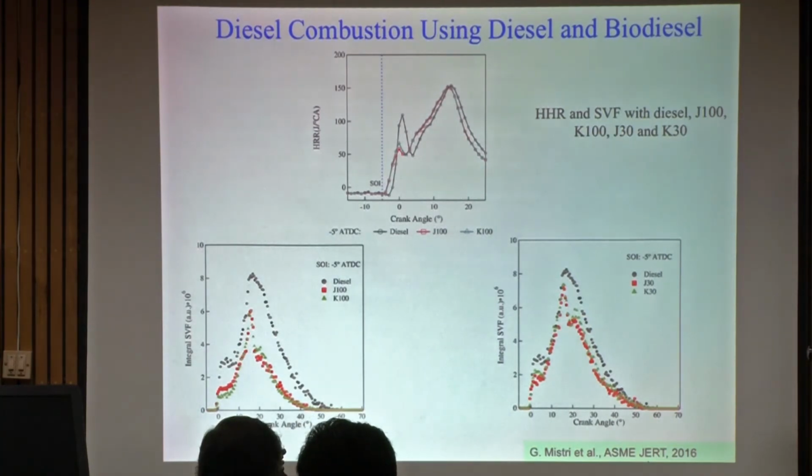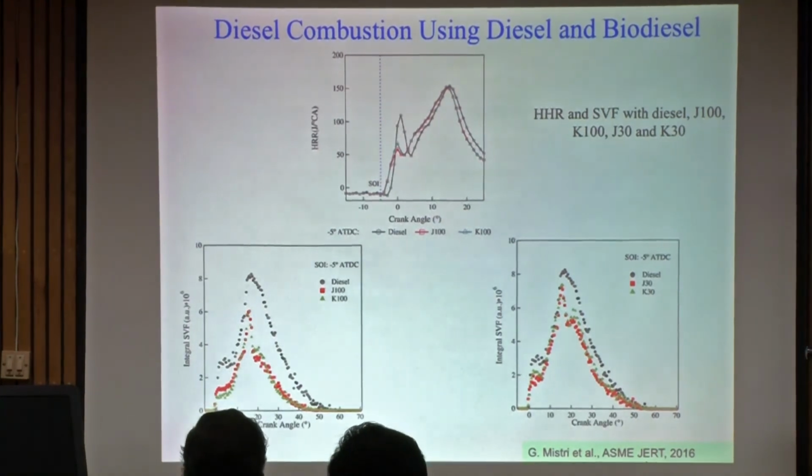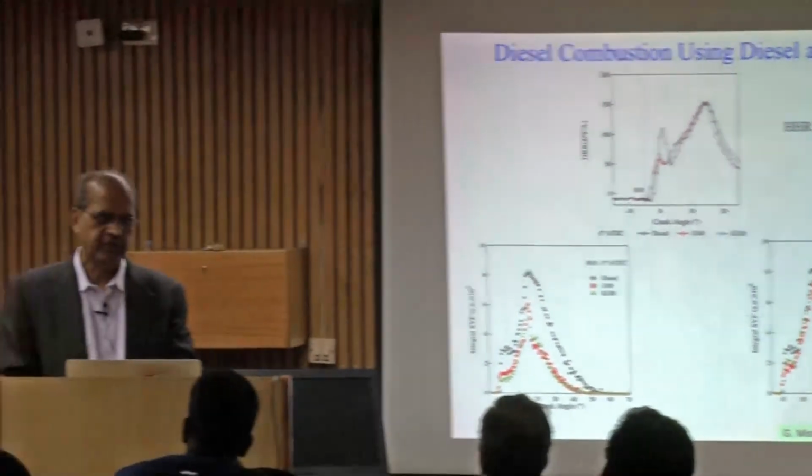So you have a lot of temperature versus crank angle kind of data. Maybe if you overlap this over the heat release rate, then, I don't know whether I have it in the paper. It may not be necessary that the temperature peak and the heat release rate peak appear in the same place. Oh no, yeah, you're right. I don't remember if I have the temperature. Anyway, any other questions? I can try to see whether there is any temperature. The temperature you can only measure either at some point or as some kind of average temperature. So they usually have some data.